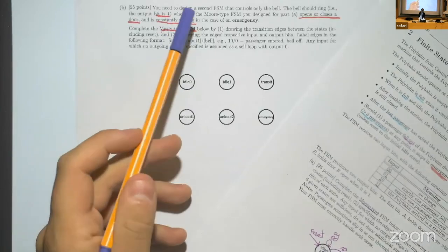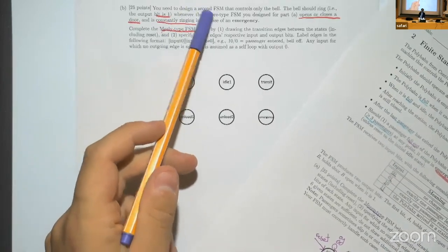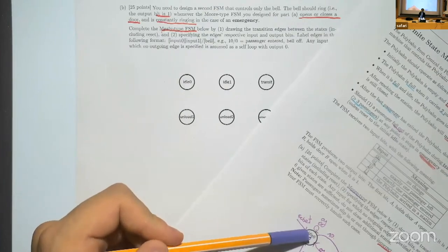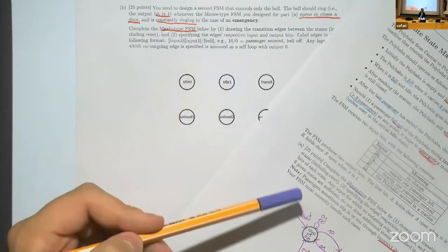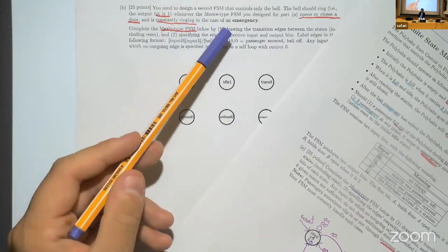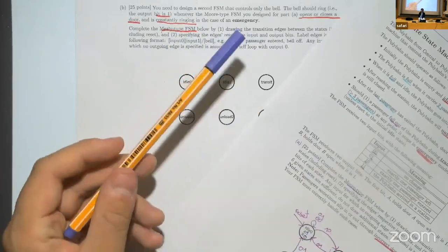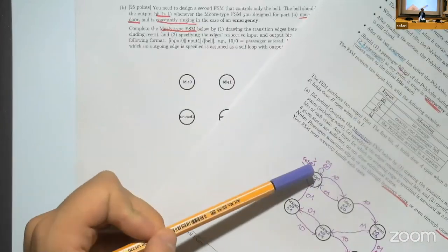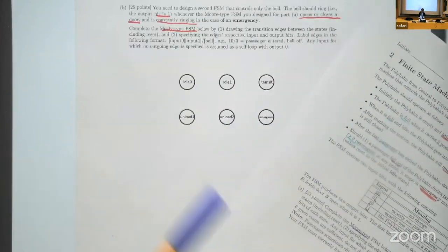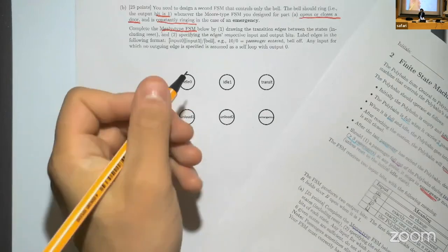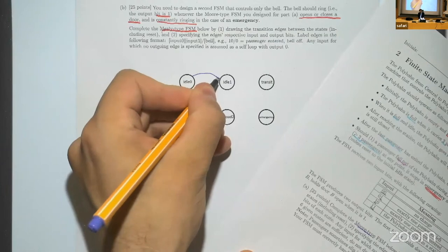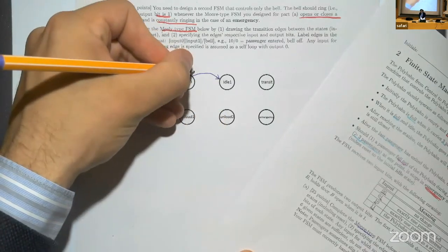You need to keep track of the same states. Somehow, every time you're in a state here, you're supposed to be in the same state over here. So you need to keep the same control logic, if you will, but your outputs need to be different because you need to have a bit 1 whenever your doors change. So what you can do is just copy all the edges for now, at least the edges' input bits.